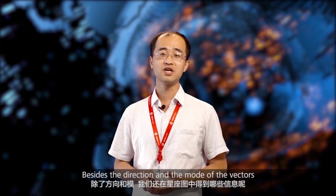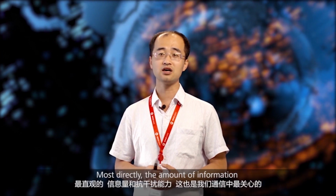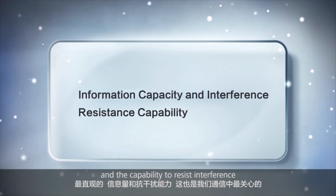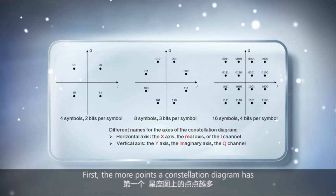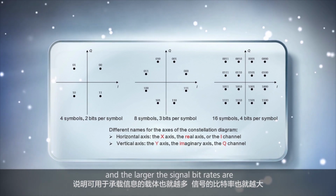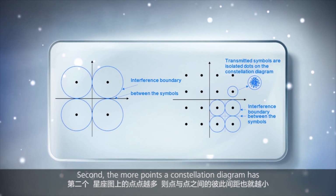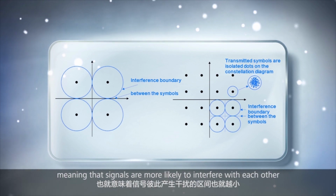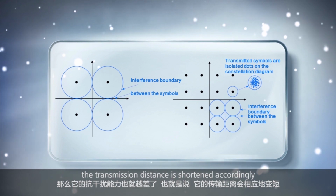Besides the direction and the mode of the vectors, what other information can we get from a constellation diagram? Most directly, the amount of information and the capability to resist interference, which are also what we care about most. First, the more points a constellation diagram has, the more information bearers are available, and the larger the signal bit rates are. Second, the more points a constellation diagram has, the shorter the distances between different points, meaning that signals are more likely to interfere with each other. With more interference, the transmission distance is shortened accordingly.